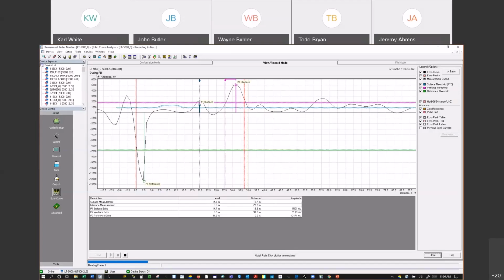You can see it put the note up here for you. It has the tag number, has the serial number, firmware version, and it'll record until you stop it. If you had to try to catch an issue that happened intermittently, then you could, if you had a way to connect this up to the radar and leave it running, you could let it run and plug your laptop in and let it go. It'll go for almost 2 weeks before it runs out of memory.